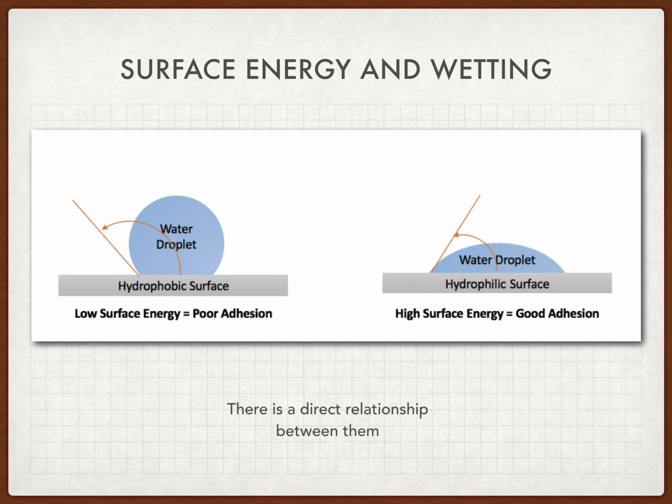We should know that the more surface energy we have, the more ability that energy has to disrupt the attraction forces between the atoms or molecules of a droplet of water or any liquid, disrupting that cohesion and making the wetting or spreading of that droplet of liquid easier. So more surface energy, less cohesion, and more wetting.